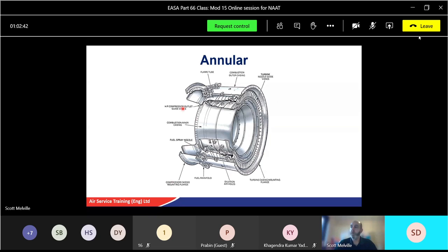All right, so there you go, HP compressor, outlet guide vanes. Okay, which again, just like inlet guide vanes, but this time they're outlet guide vanes. Then you've got your large inner combustion casing. You'll have the fuel spray nozzles, the burners going in. And now there will be burners all the way around. Just because it's one big can, it doesn't mean there's one burner. There will be at least maybe 8 to 10 burners going around. Again, dilution holes, etc. And then eventually, again, you can see here the nozzle guide vanes.